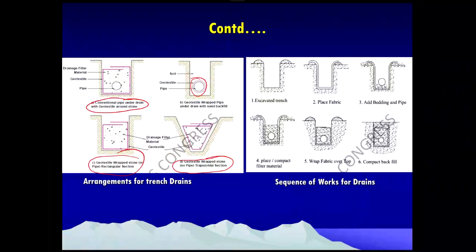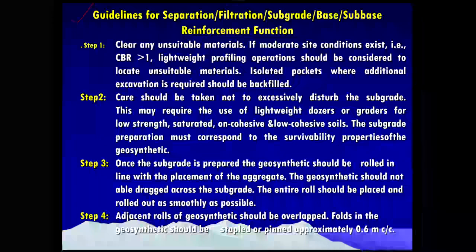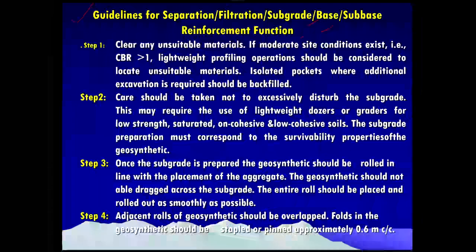For this, we have a sequence of activities: excavate the trench, place the fabric, add the bedding materials, place and compact it, wrap the geotextiles, finally fill and compact it. So this is the procedure which is given. You can go through the material which I'm going to supply, and guidelines for separation, reinforcement for the base, subgrade, and the reinforcement function are also given.